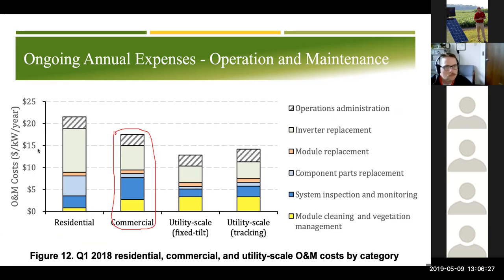But currently, at $15 per kW annually, for a 50 kilowatt system, you're spreading that cost over 25 years, so $750 a year that we're allocating towards O&M. Not that you're going to use it every year, but you're accounting for it in case you do have a major component failure.